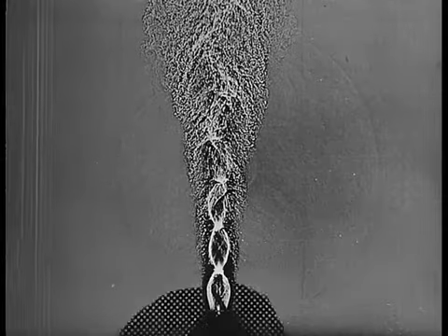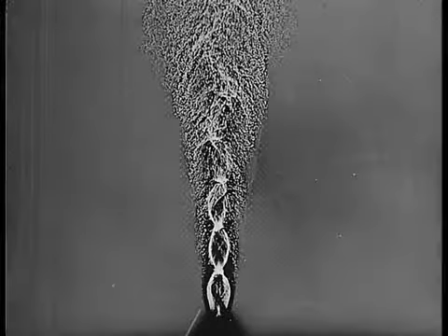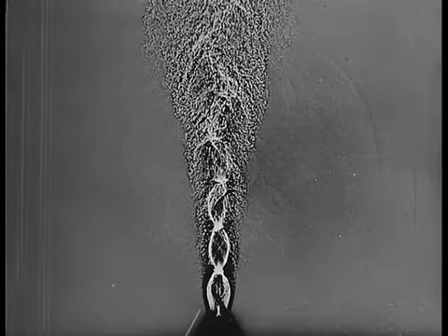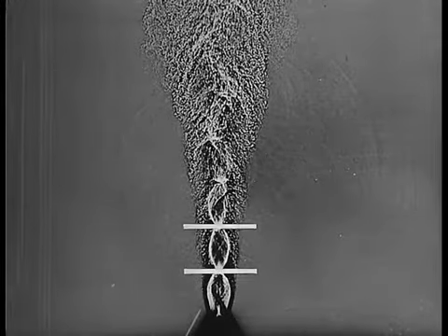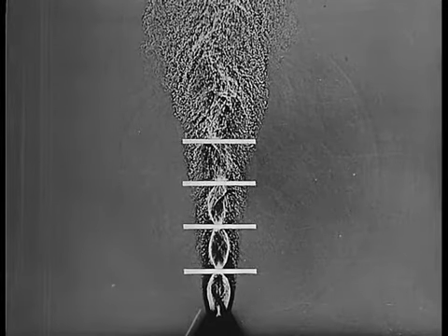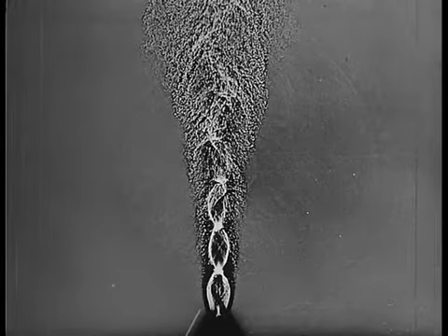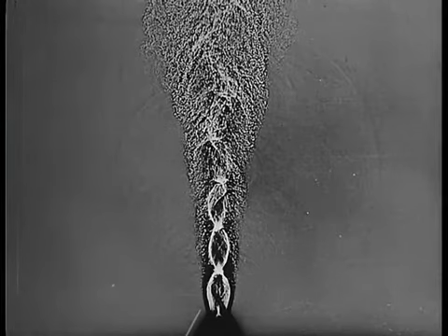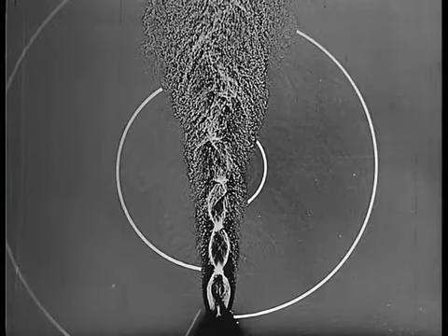First, the flow field. You can see the nozzle exit, the cell structure, shock waves, and the boundary layers. The turbulent structure is well discernible. In the sound field, these cylindrically outgoing sound pulses are most striking.